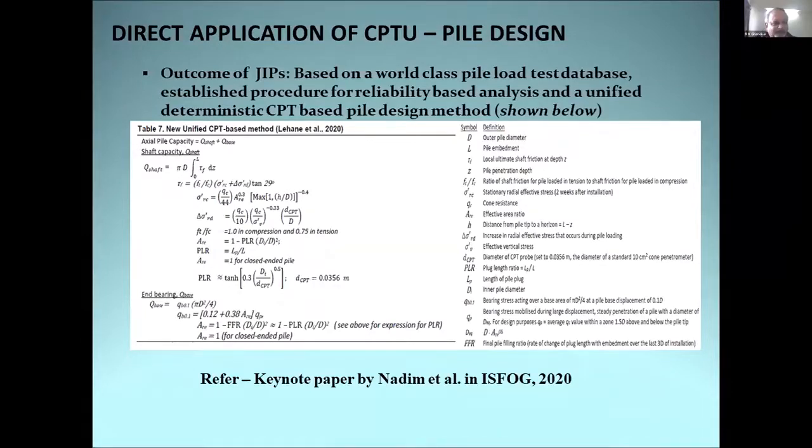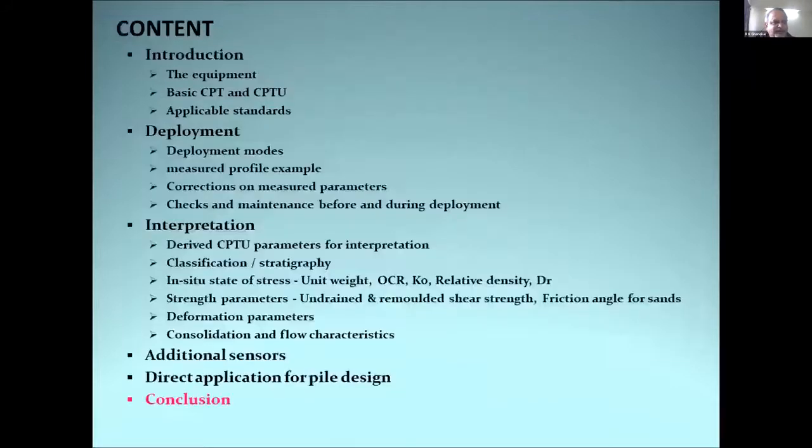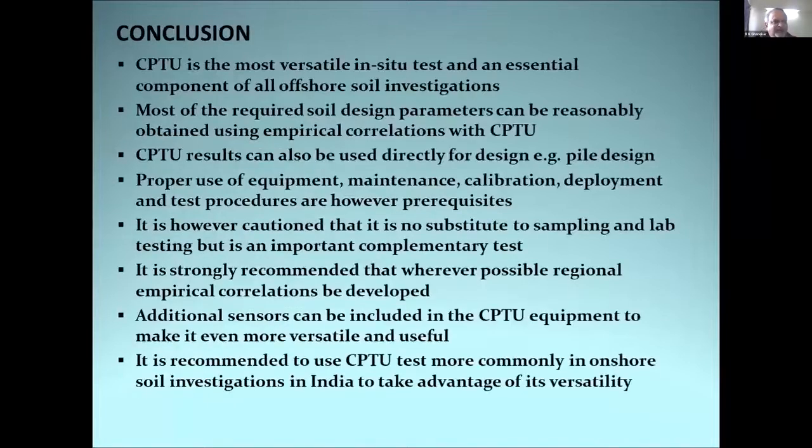For more details, you can refer to the keynote paper by Nadeem et al. in ISFOG 2020. Now coming to conclusion, CPTU is the most versatile in situ test and an essential component of all offshore soil investigation. Most of the required soil design parameters can be reasonably obtained using empirical correlation with CPTU parameters. CPTU results can also be used directly for design, pile design.